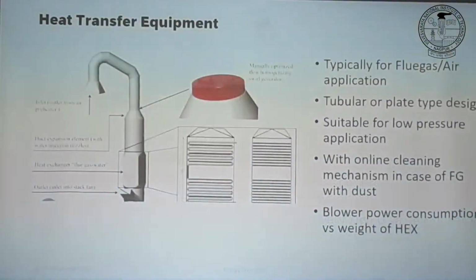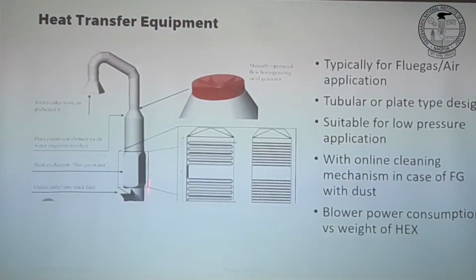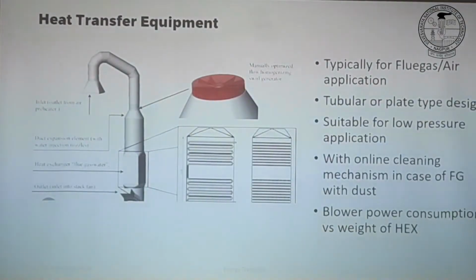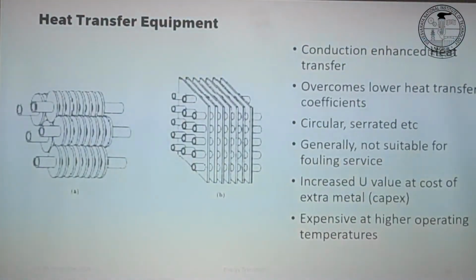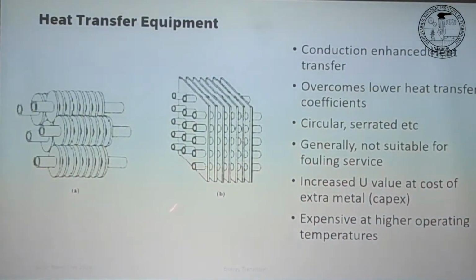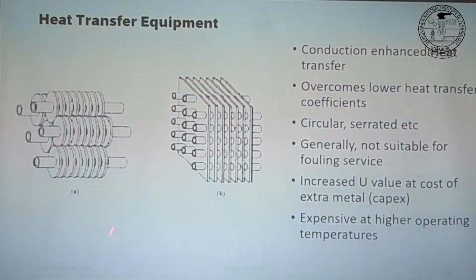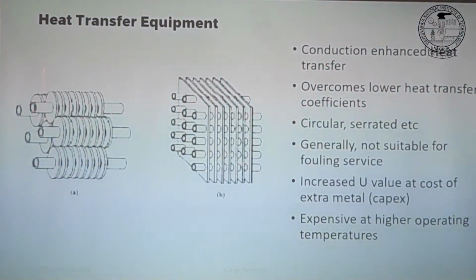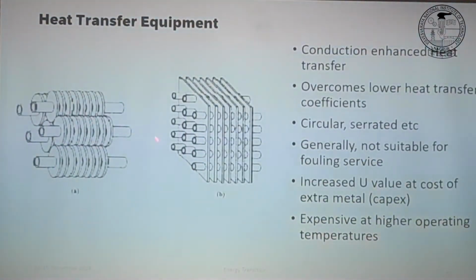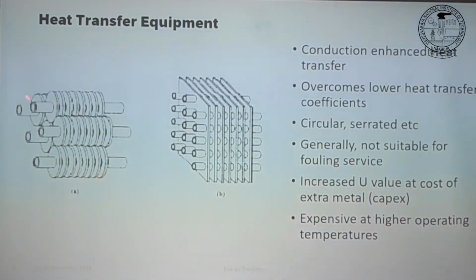Then we saw we have huge exchangers here, a lot of area required, and that's one way: reducing the area or increasing the transfer coefficient. You have extended surfaces, so you just put in metal, and the cold side or the hot side can transfer heat via convection, and you enhance it via convection.